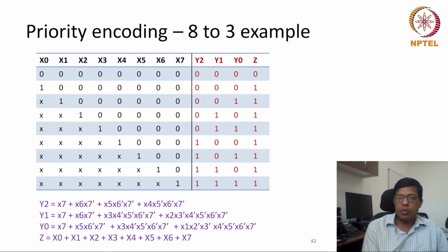For example, in this particular expression, whether this x3 value is 1 or 0, it is true that the output is going to be this. So that means it will get optimized away. Finally, when we write a K-map or QM sort of method, because x3 as well as x3 dash are both part of this input pattern, it is going to optimize away. So that's why these x's have a different meaning, than if we have an x or don't care condition at the output.